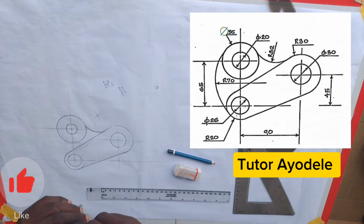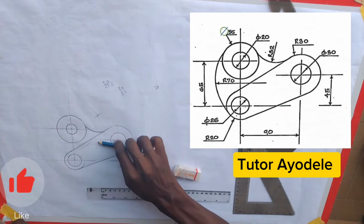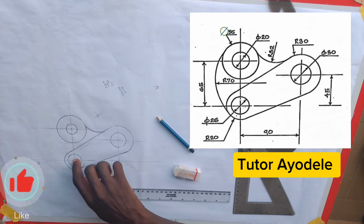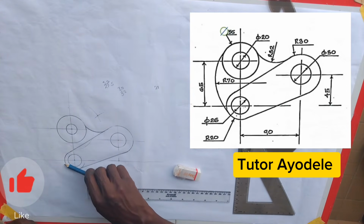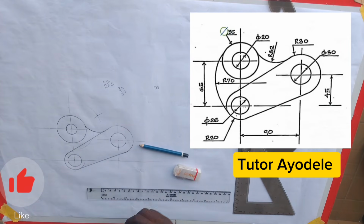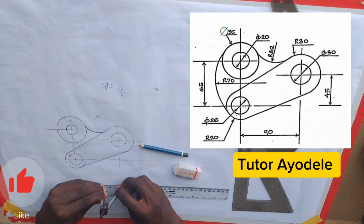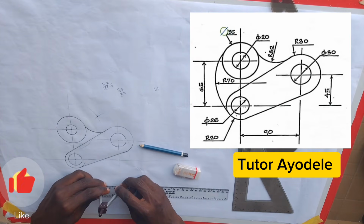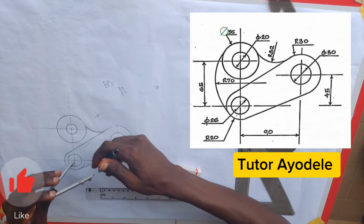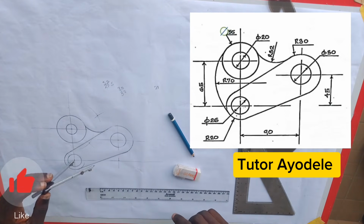Okay. Now you will see that for this side too, I will subtract the radius of this bigger circle from the radius of this arc. The way I subtracted this, the same thing is also applicable to this. So the radius of this bigger arc here was given to be 20, right? So I will subtract 20 from 70, and that will be 50. So 50 millimeter is the same thing as 5 centimeter. So I will place it here. I will mark another arc where they joined here. The two of them joined together here. That is the midpoint of that arc.